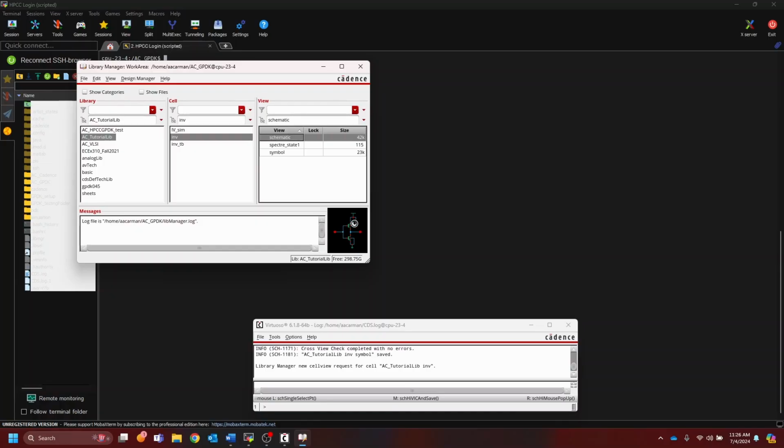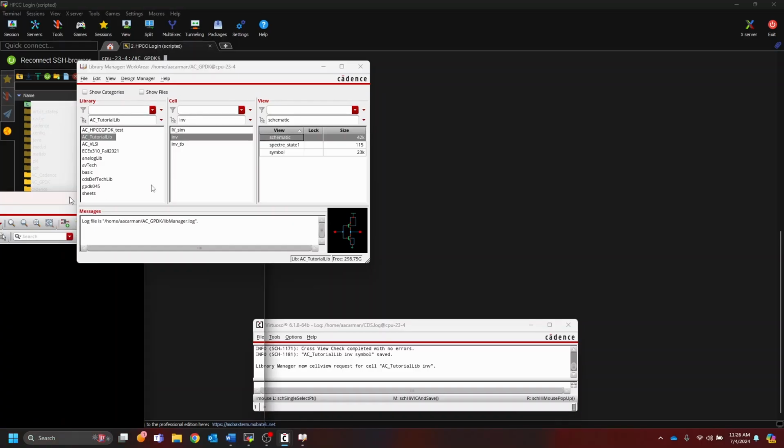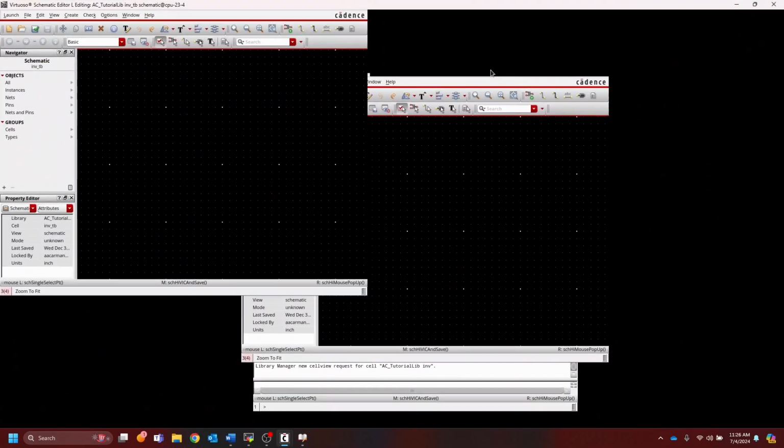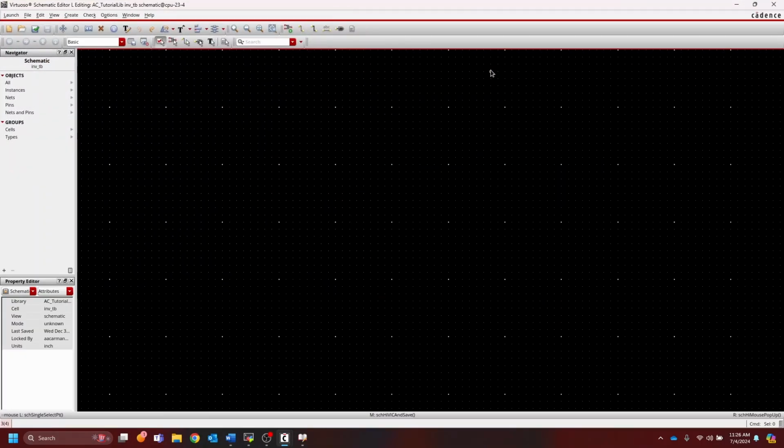So we can keep our inverter schematic pretty much exactly what we want it to look like on chip, where we have just 2 transistors. And then we can make our own cell view where we test our inverter, so we can have all those ideal voltage sources, things we can't realize on chip outside of it. So we're only testing our inverter.